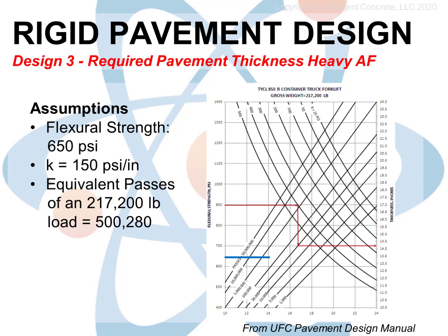We can see here that if we'd used a K of 400 psi, we'd end up with a concrete thickness of about 20 inches, which seems like a lot, but is actually not that crazy for a heavy airfield pavement. This discovery might or might not be our solution, but it does give us an indication on whether or not we could have a solution available.